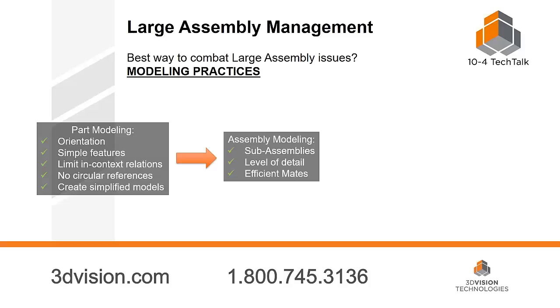When you get to the assembly, make sure you use sub-assemblies as much as possible. Have an appropriate level of detail, so you don't want to be able to zoom in and see nuts and bolts on a huge assembly of a factory plant.